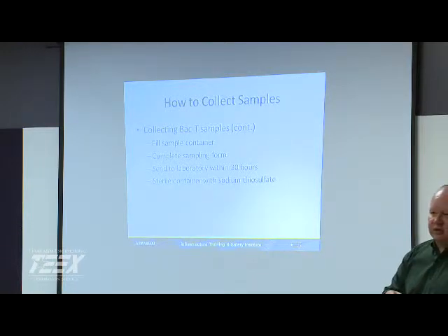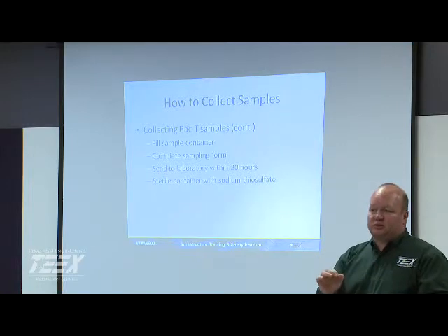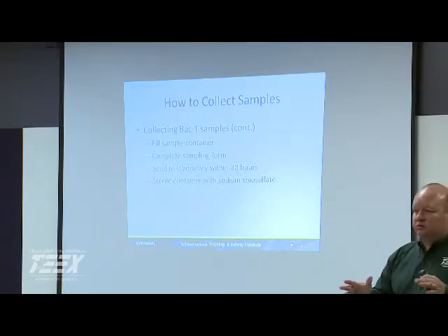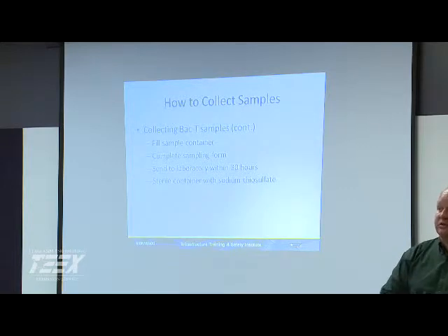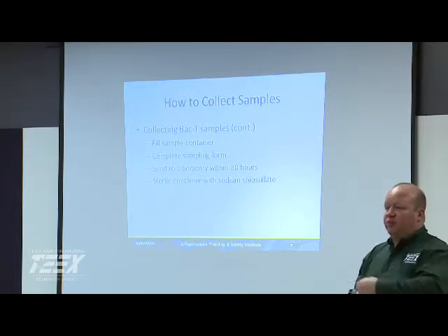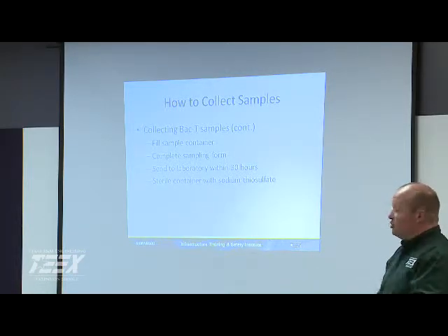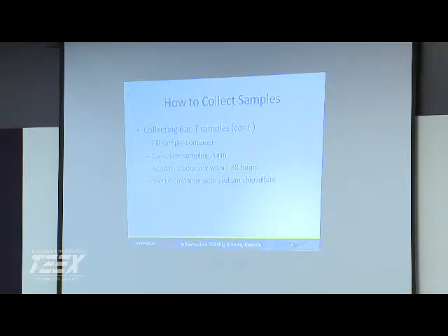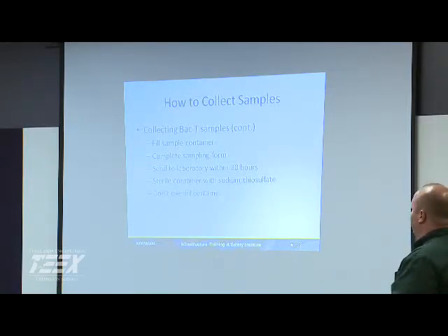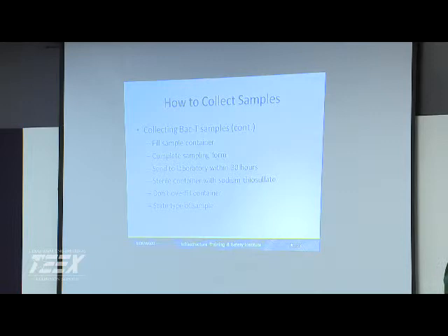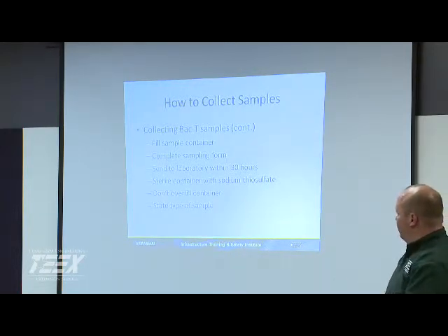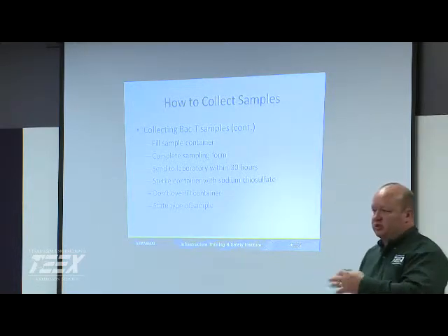We know how much chlorine the sodium thiosulfate tablet will neutralize. Do you have an idea? About 10, 15 parts per million. About 15 is what IDEXX talks about. So if you have a pretty hot sample, you can still neutralize it. They really go above and beyond. You shouldn't have that much out in the distribution system, but if you're pulling special samples, like construction samples, you can still get away with having an elevated residual. Obviously, we don't want to overfill it. If you do, get a new one and start over. You're done with that one. And then we talked, Tennessee is interesting with the way the sampling is.